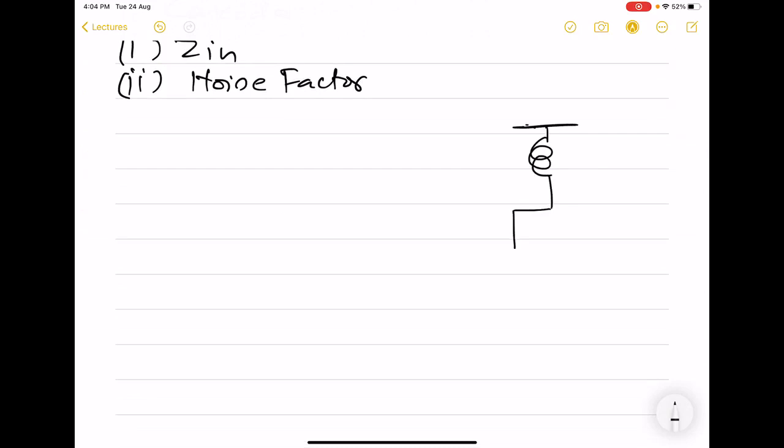So we are familiar that this cascode is basically a cascade of a common source. And as the name suggests, this is an inductively degenerated cascode. That means the source of the first MOS M1 is degenerated by an inductor.